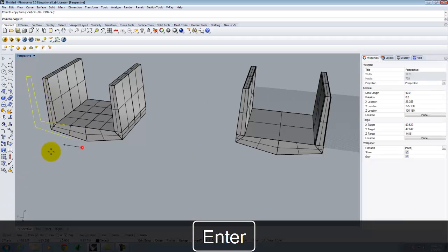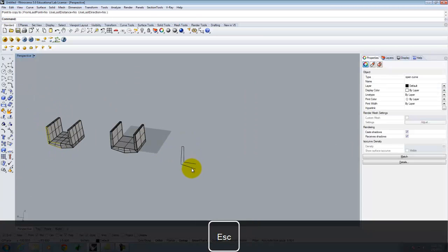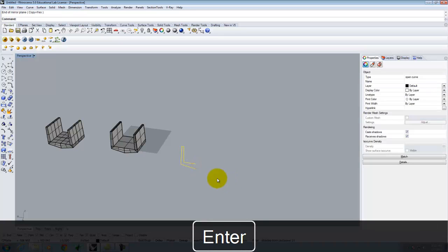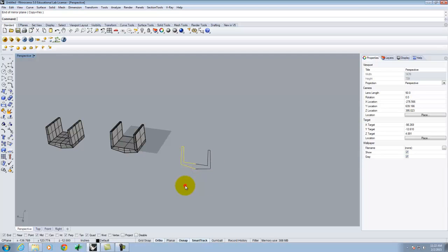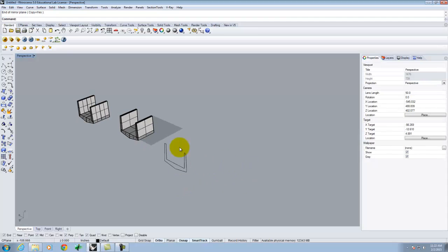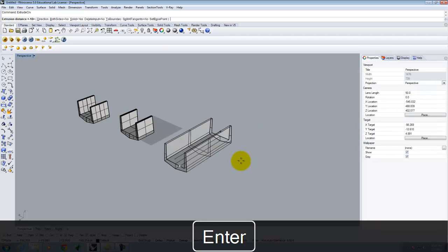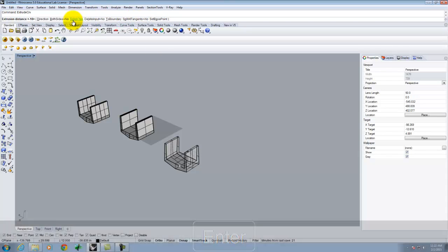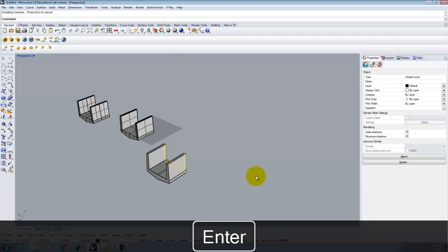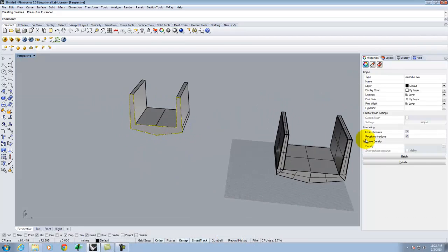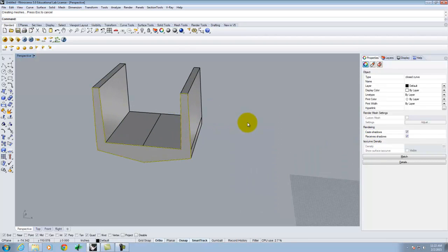and let me copy it. Hold on a second, and let me mirror it. Oops. All right, so I have that. Let me join it together. Okay, now if I'm going to extrude this, extrude curve, right? Making sure that it's solid. Yes, I could go back and say 4 feet. Oops, that was opposite direction, and it created the surface. Okay, nothing wrong with that. But these chamfers I'm still going to have to go back and do.